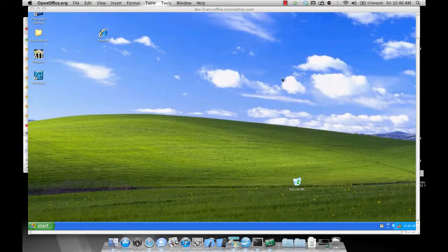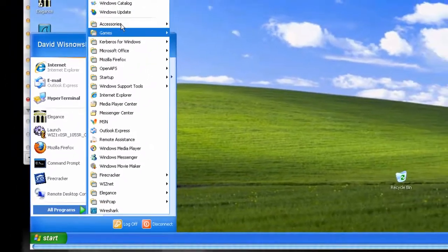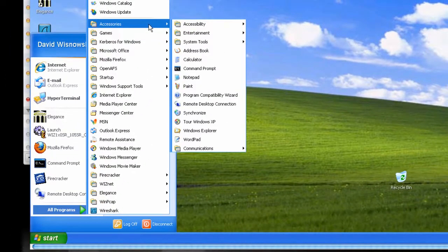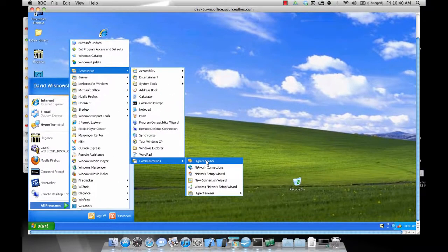First, open a hyperterminal application or any other terminal application you choose. On Windows, you can find this by navigating through the Start menu to All Programs, onto Accessories, continuing through Communications, and finally to the hyperterminal application. If you do not have this application, you can download an alternate terminal program such as Hyperterm or TeraTerm, just to name a couple.